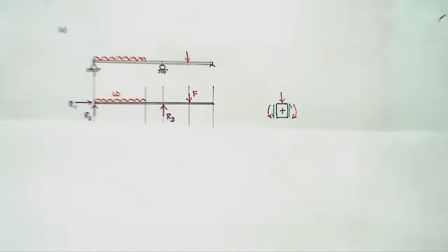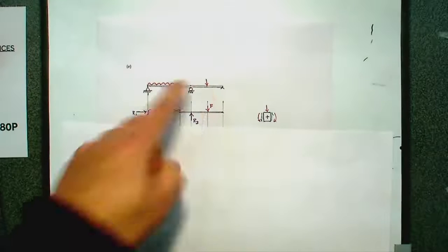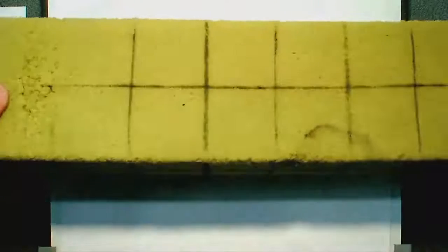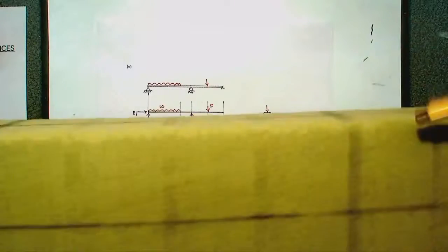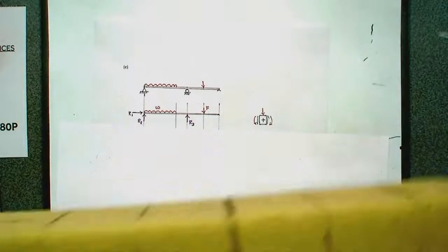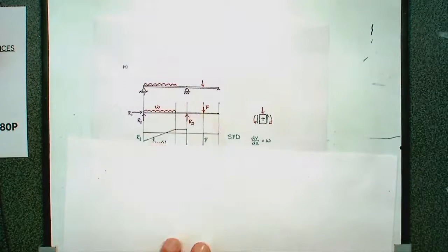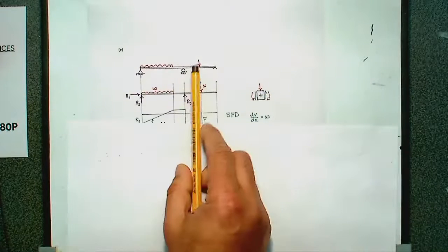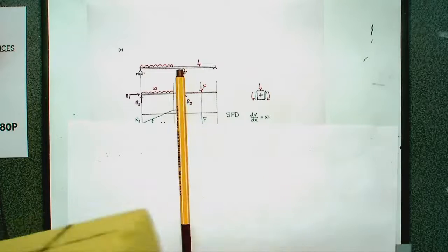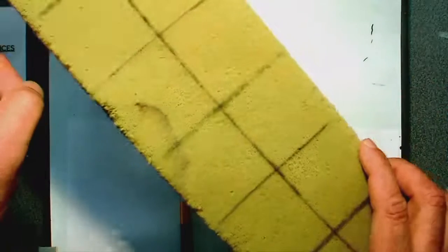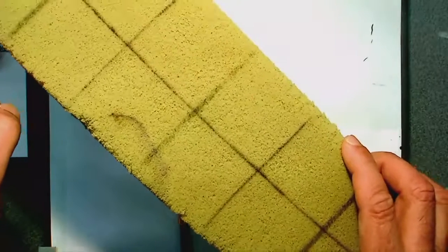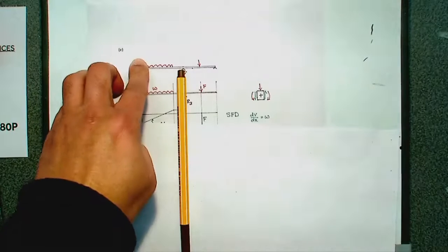But what happens when you consider that point load, what does it do? The point load is here on the right hand side, and you have got two supports. So what is the effect of the point load with respect to the right hand support? If you consider your pivot or lever here, and you have got this beam, and you are putting a load onto this side, then the other side will try to lift off. So this support will try to lift off, for example.